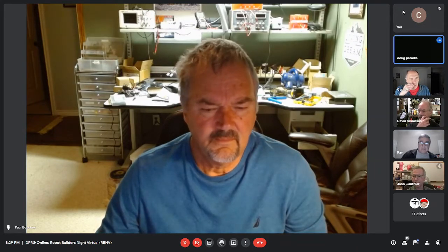Brian, you're muted. Is there anything you can get off the shelf that serves as a good cable for a long I2C cable? Kareem's put something in the chat here on Crosstalk. Yeah. In terms of, you said cables, I don't know, John. There is a possibility, Paul, if you've got a big junk box, you might have an old serial cable stuck somewhere in your junk box, which would allow you to just use it, and it's as shielded as it can be. In the old-fashioned days of PCs when they had serial ports, a 6-foot serial line was not a big deal.